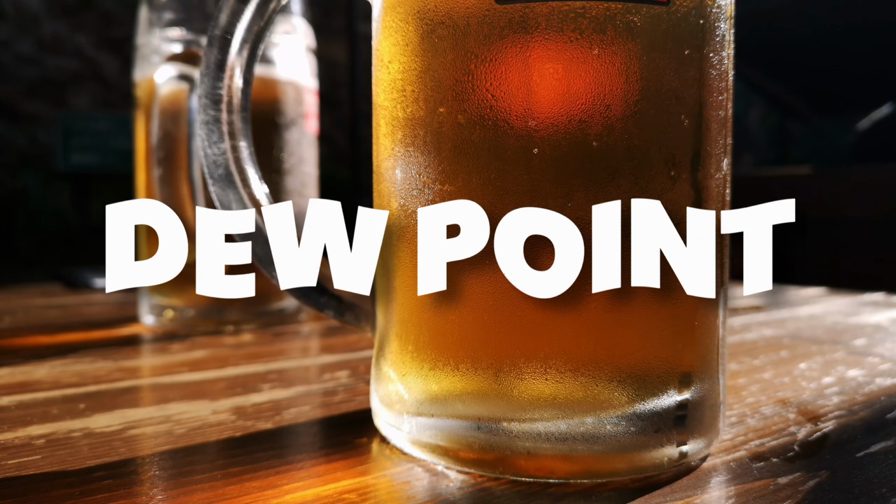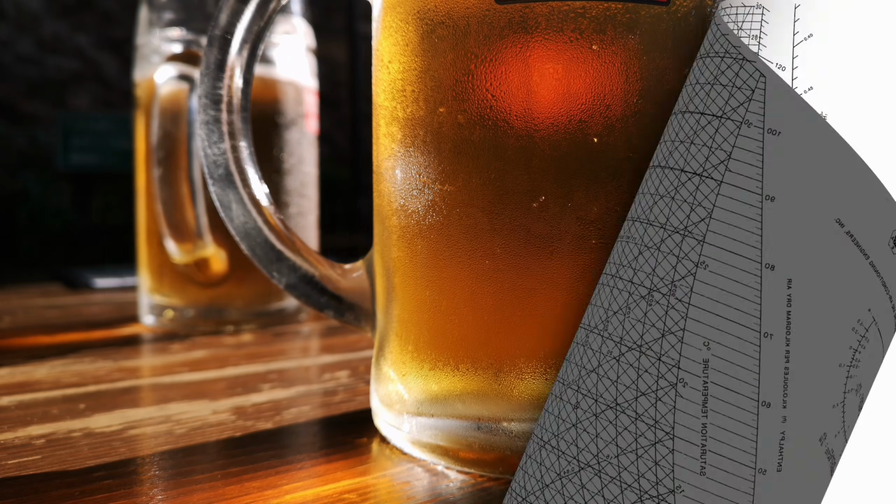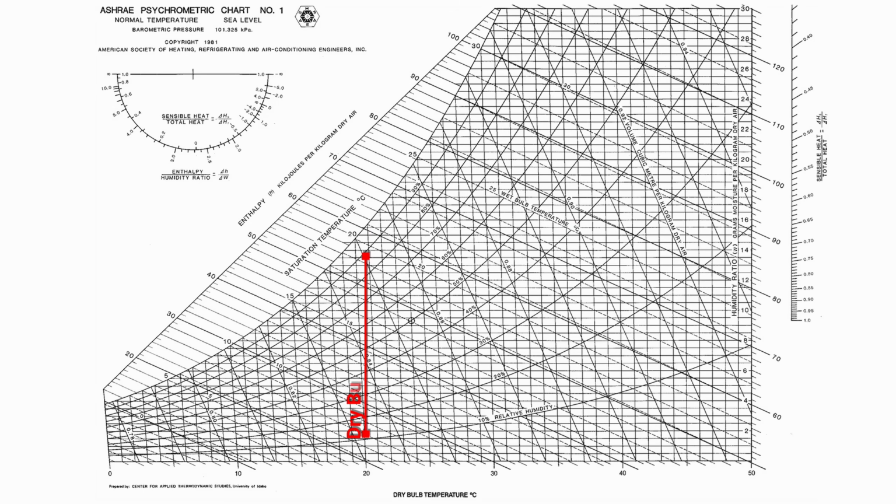Now let's talk about the concept of the dew point. On the chart, for any given dry bulb temperature and humidity ratio, there is a corresponding dew point. This point lies along the liquid vapor saturation line, the place where the air is fully saturated with water vapor.